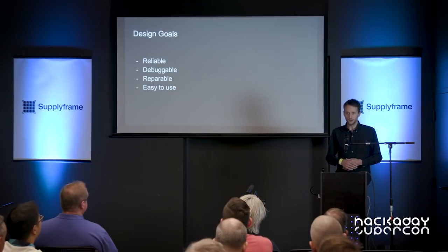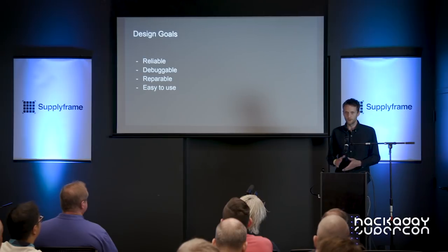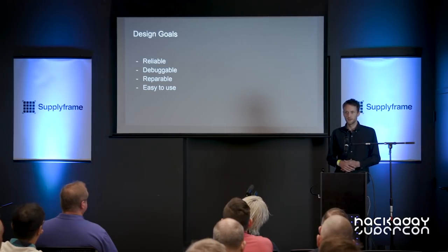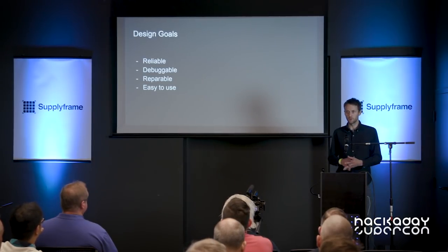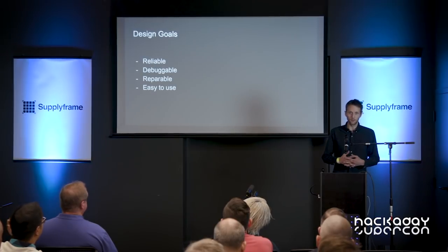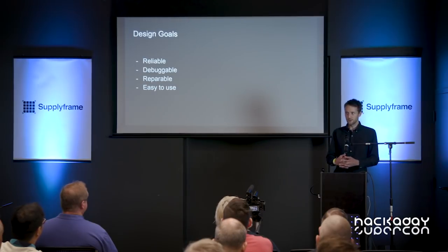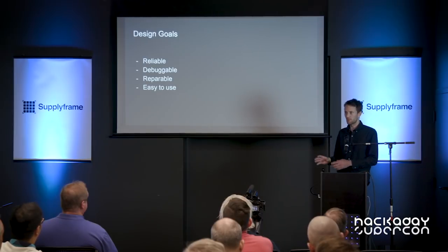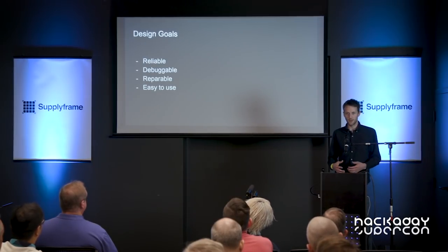So I designed the software so that there are no loops anywhere. There's the single top-level loop, so there's no part of the software that could steal all of the CPU time. Stuff like this, so that I hope to get some confidence that things would keep running, and even if things go wrong, it wouldn't go catastrophically wrong. To make things debuggable, I added the ability to test every specific component of the system. So if it breaks, you can check each part one by one and see that it is okay, and hopefully isolate the problem and fix it.